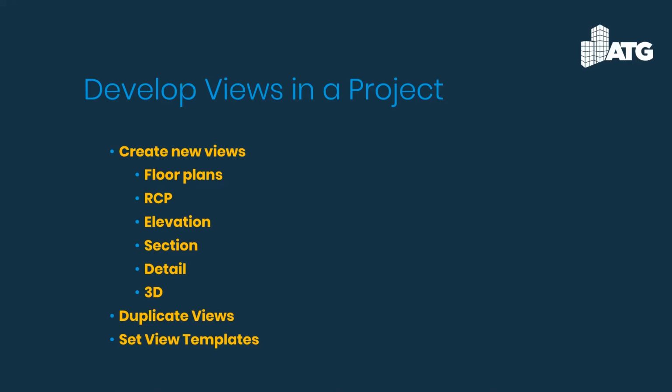The last thing, again, I want to touch on is setting the view templates. I do think that is a very critical aspect of Revit to keep your drawings, your views consistent. So when you do go in and develop each of these new types of views, it's a great idea to go in and apply a view template to it right away. So what you're doing is you are applying the company's settings to that view right away. So you know that what is going to be on that view is going to be correct as far as the objects that are being displayed and how they're being displayed within that view.